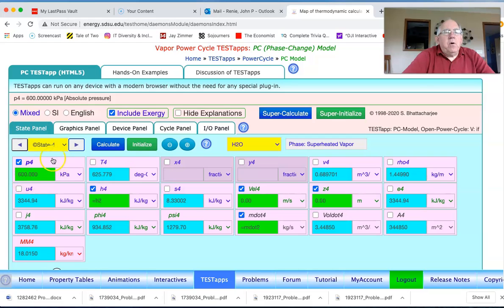And so state 4, it's been stated, is operating at 600 kPa, which was the extraction point of the turbine. And so state 4 is an isenthalpic expansion, and so the enthalpy stays the same. The mass flow rate is m dot 2, which is the 5 kilograms per second. So that's state 4. State 5 now is going to that pressure, that P4 extraction pressure.